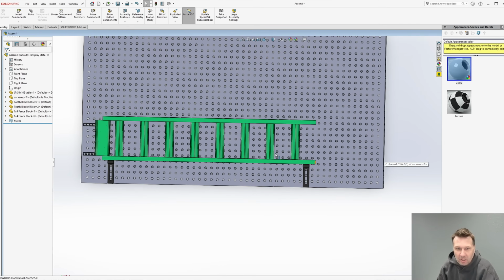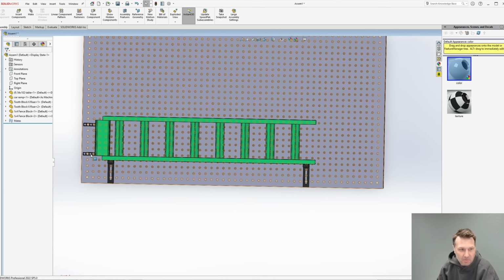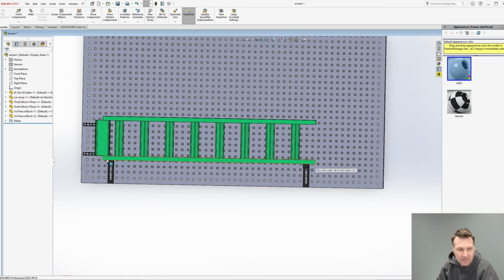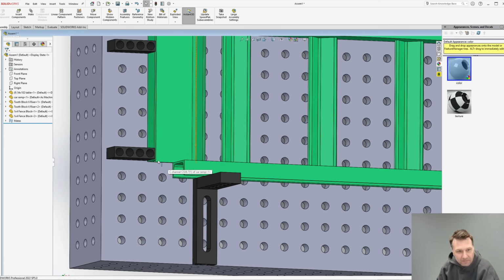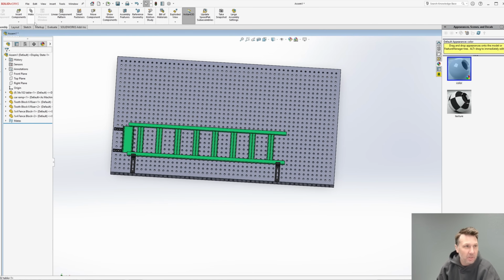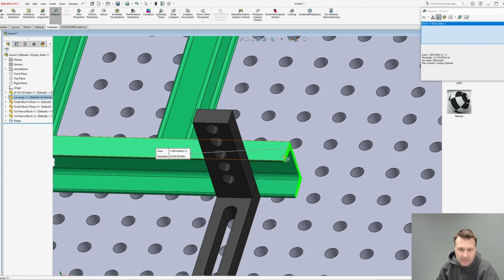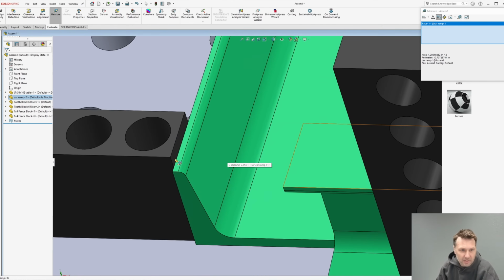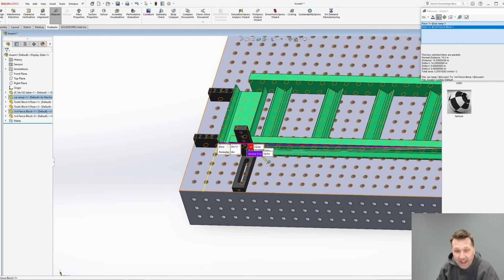And we want overall length to be exactly the same. So we're going to endo this end over here. Okay, whatever happens over here, we can kind of float a little bit because it's like a welded joint per se. Now, what are we at? So in SolidWorks, we can do a measure. We can go to evaluate, hit tape measure, that there to this here, 74.5.